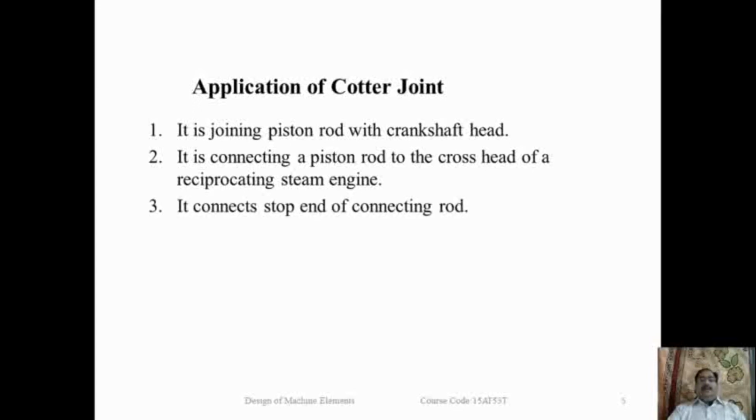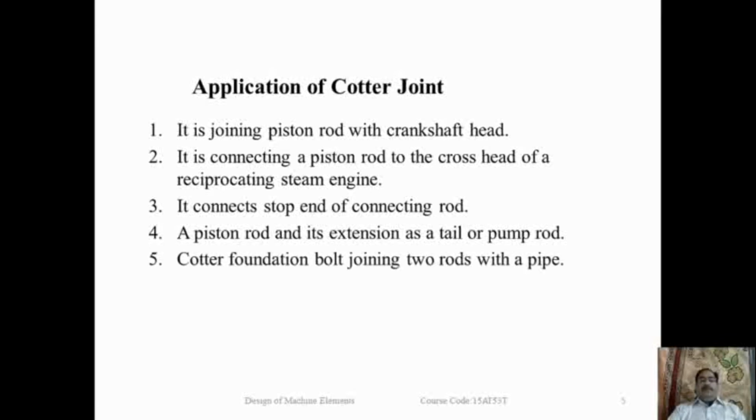Third one, it connects the stop end of a connecting rod. Fourth one, it connects a piston rod and its extension as a tail or pump rod. Fifth one, foundation bolt, joining two rods with a pipe. So these are the applications of the cotter joint.